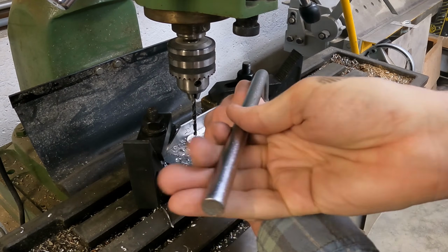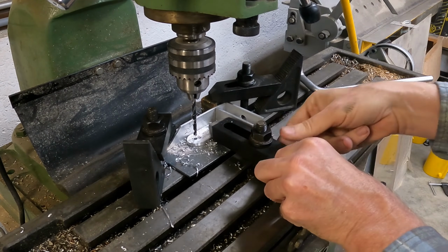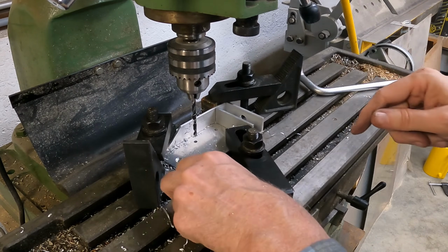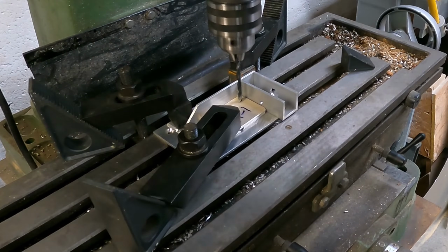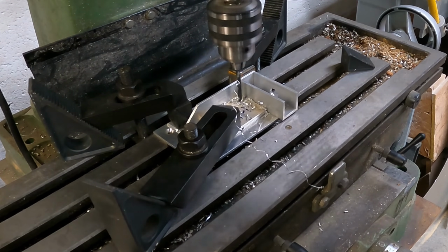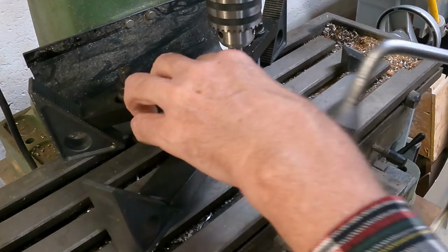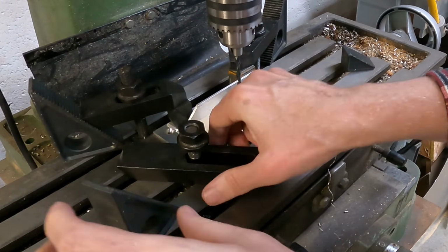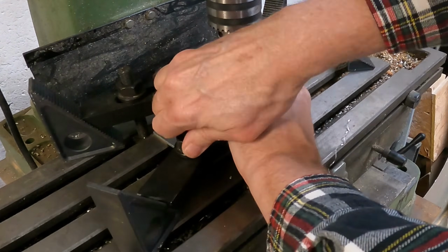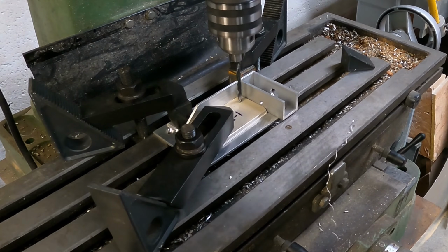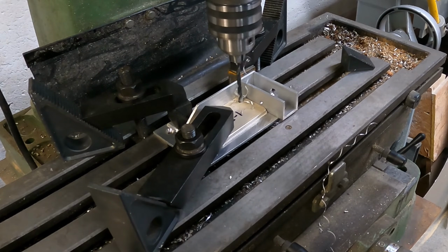They don't have to be super accurate, but I am going to make it accurate anyway. And I got a little jig here to help me do that. Now, I can't really eyeball where to put these holes. First, these load spreaders are each in pairs, and so the holes have to line up exactly right so I can get bolts through them. And then number 2, those holes have to be the right distance from each other in order to get the load spread correctly. So I'm going to use my vertical mill here and the table on it in order to get those holes in the right position.